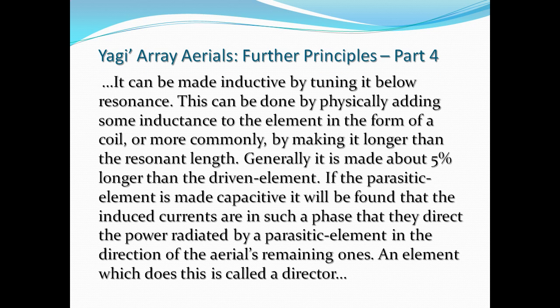If the parasitic element is made capacitive, it will be found that the induced currents are in such a phase that they direct the power radiated by a parasitic element in the direction of the aerial's remaining ones. An element which does this is called a director.